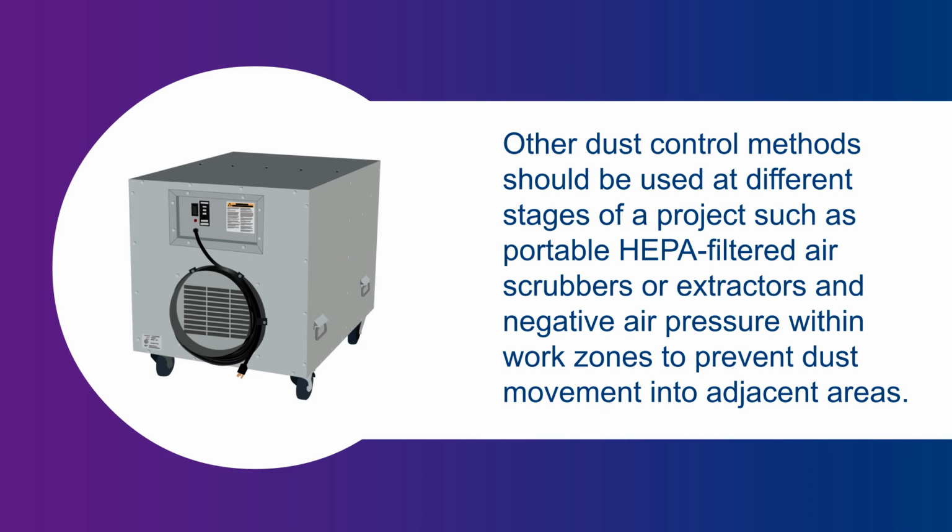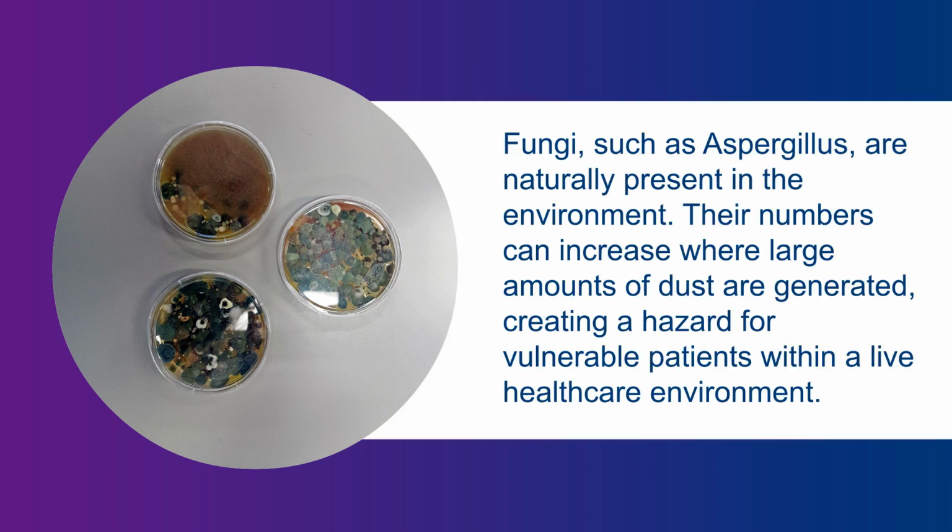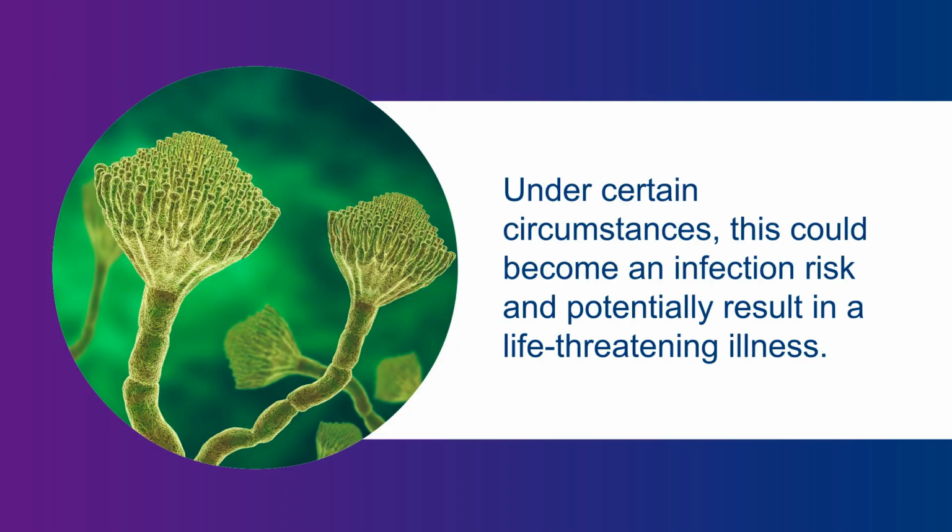This may include the use of portable HEPA-filtered air scrubbers or extractors to capture airborne particles during work, as well as negative air pressure within work zones to prevent dust movement into adjacent areas. Fungi such as Aspergillus are naturally present in the environment. Their numbers can increase where large amounts of dust are generated, creating a hazard for vulnerable patients within a live healthcare environment. Under certain circumstances, this could become an infection risk and potentially result in a life-threatening illness.